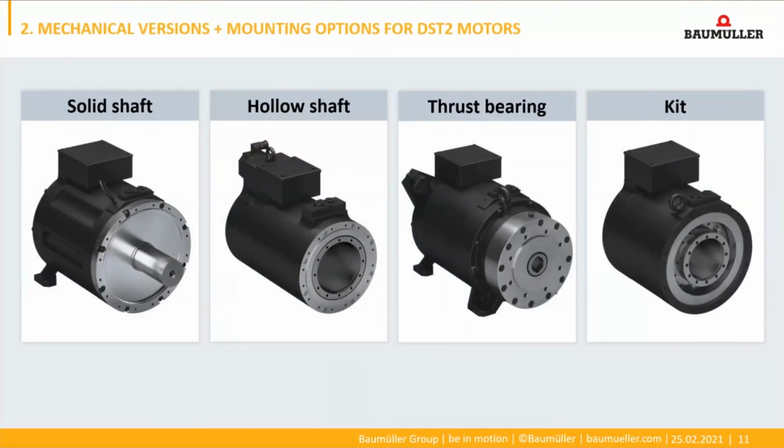To briefly go into the inner values, these motors are high-poled synchronous motors. Highly poled for the reason that you need high torque at low speeds to replace motor gearbox solutions. Our torque range starts from 140 Newton meter up to 60,000 Newton meters.